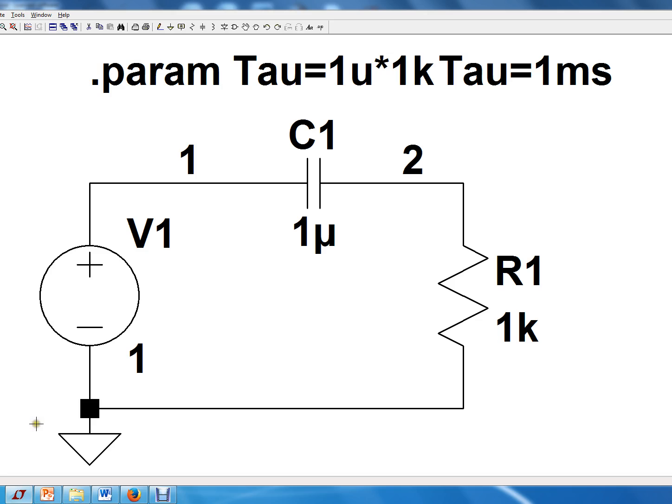Sorry about that. So what we have here is an RC circuit, but usually in books they start off with the capacitor here and the resistor here. And this turns out to actually be a high-pass filter. We can think of it in this way: this impedance and this impedance make a voltage division. This impedance gets smaller with frequency, and so ultimately as the frequency goes up, the voltage at 2 gets very, very close to the voltage at 1.